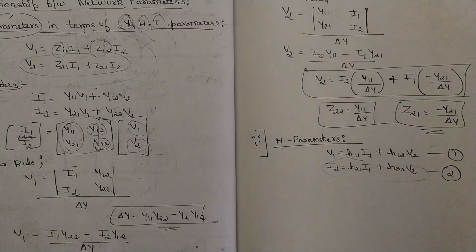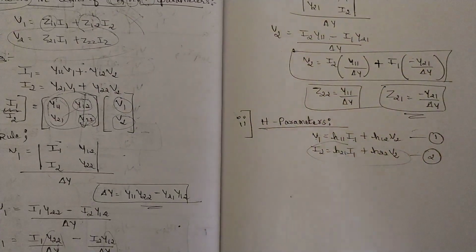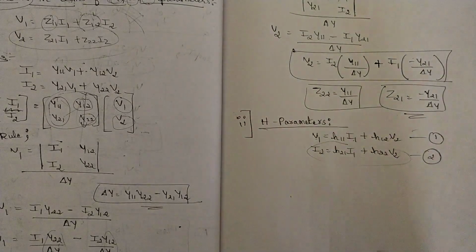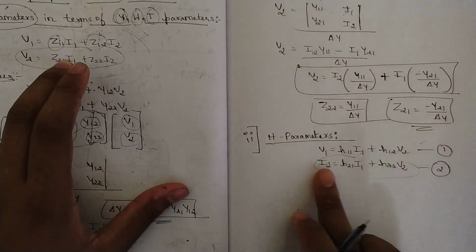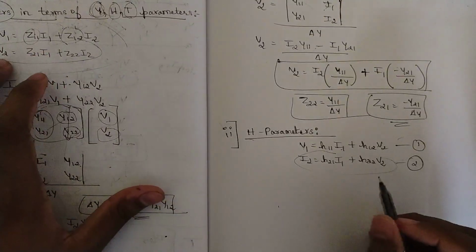All the terms are not common. In this kind of problem, in this kind of direct solving using the equations, the first step is to compare which pair of equations have the same variables. Check that. So here I told you, the second equation of the z parameters and the second equation of the h parameters, which I have written, have the same variables.